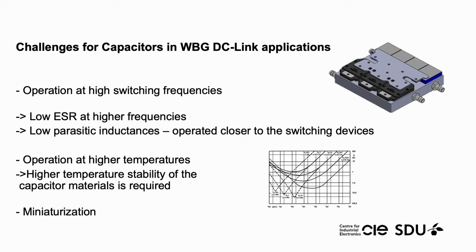To reduce the parasitics, it is needed to connect the capacitors very close to the hot switching devices. That means that the temperature stability of the used capacitor materials must be as high as possible, or using sophisticated active cooling means. Last not least, the miniaturization trend of the wide bandgap devices demands also an ongoing miniaturization trend for the passives and therefore, of course, for the capacitors.